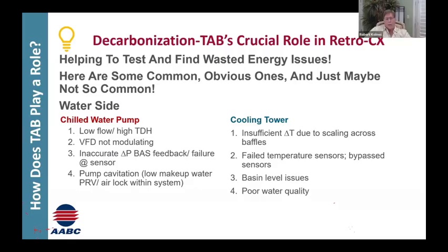Right, like in chilled water pumping here, low flow, high TDH is common. You see that quite a bit. But what's going to lead to this condition? If you're going to start there at the pump, you've got your triple duty valve. I've seen where the check valve portion of the triple duty valve has stuck, whether fully closed or partially open, and the contractor there gets his hammer and beats the heck out of it, or we just change it out. You may find on the existing building where you came to that same valve that somebody's trimmed it back for whatever reason. Yep. It could be just as easy as a dirty system where your suction diffuser may be impacted.